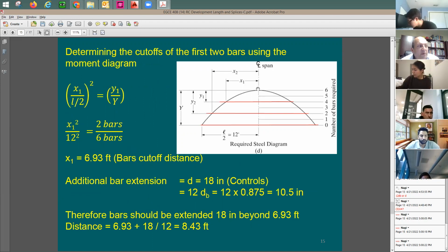Okay. So from this point here, for this rebar to stop it, I need to extend for L sub D to be able to take the bar or the tension out of it and bring it to the concrete. And you need the distance of L sub D. So here now, this gives me the section of maximum moment. Now I need to stop the bar.